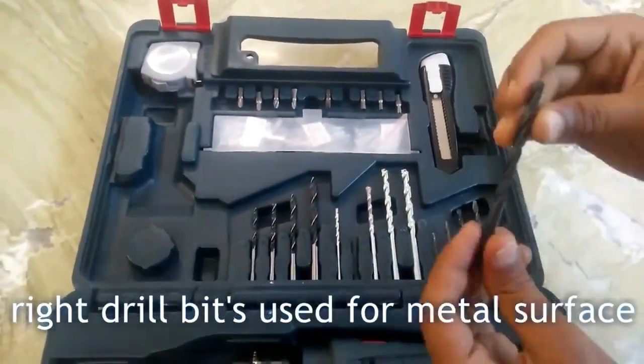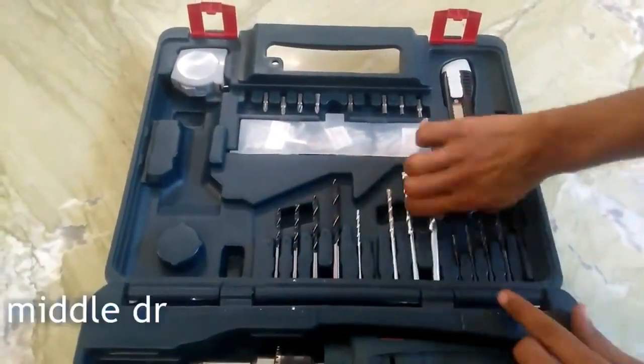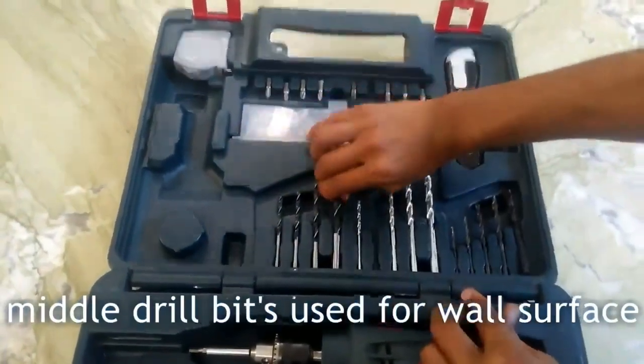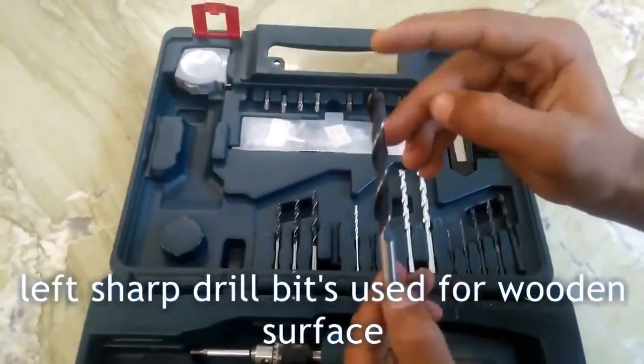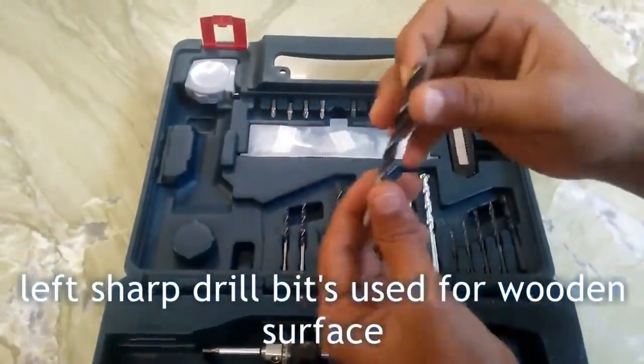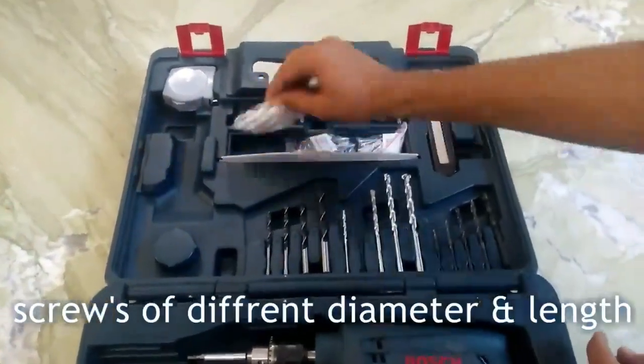These drill bits are used for metal surfaces, the black ones. These middle ones are used for wall surfaces, concrete. And these drill bits with the sharp end at the tip, they are used for wooden surfaces. We are going to use these drill bits for our carpentry operation.